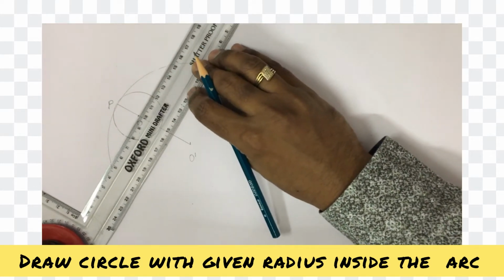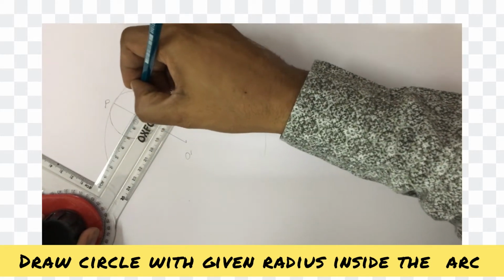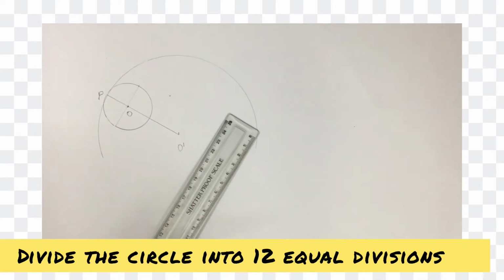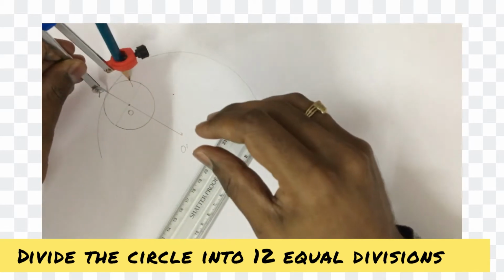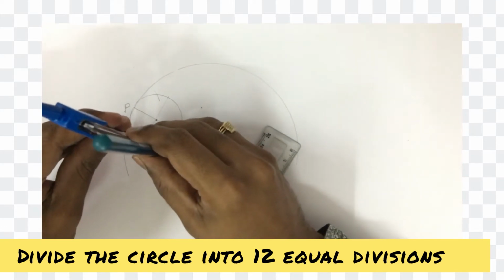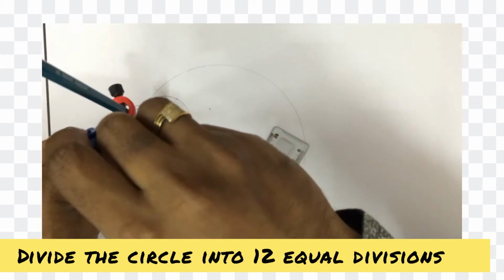Later we are supposed to divide this circle into 12 equal divisions. We know how to divide the circle into 12 equal divisions. So this is how we are supposed to, this as a center, cut arcs either sides. I hope you know how to work out the division of a circle. Next, this point as a center, cut the arcs either sides of the circle.